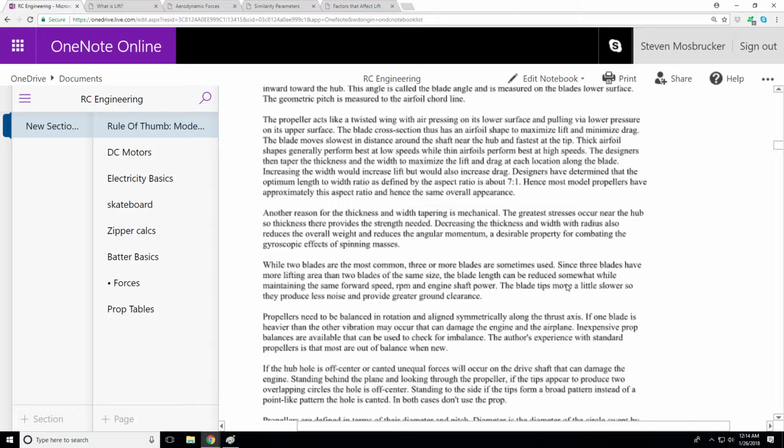And the other idea why blades are gigantic, again, is because of the drag, and number two is because when you have a rotating mass, when you try to accelerate very quickly on a propeller airplane, especially an RC airplane, it takes some time to spin up to speed. Now the heavier to change its speed, the more mass it has. Force equals mass times acceleration.